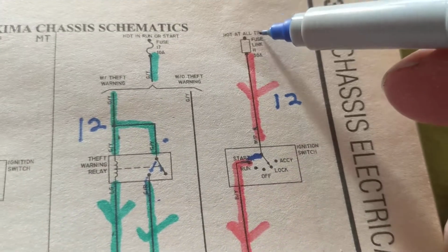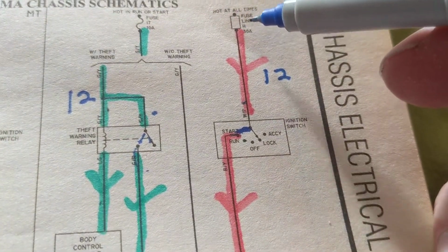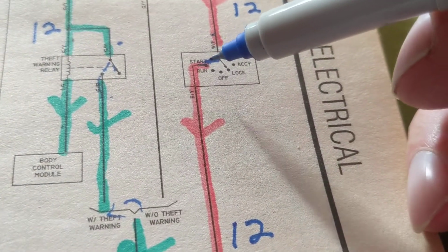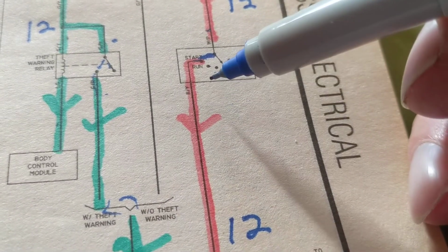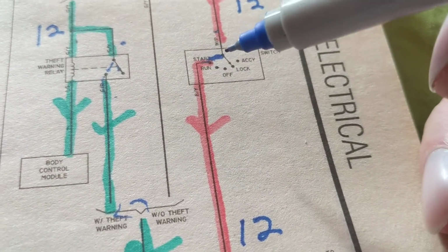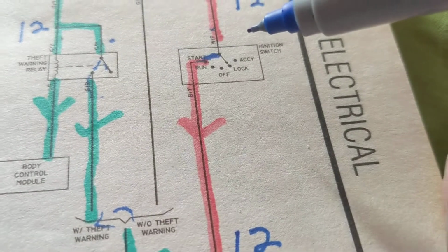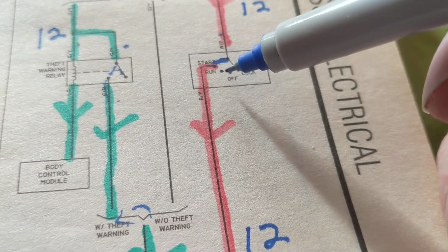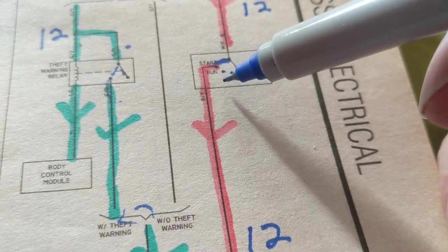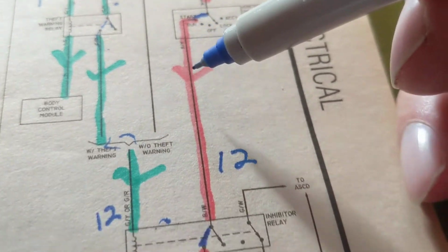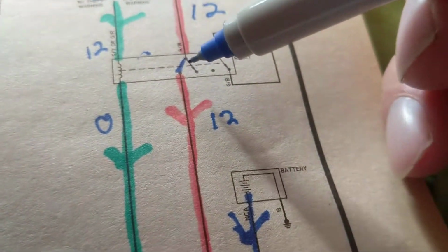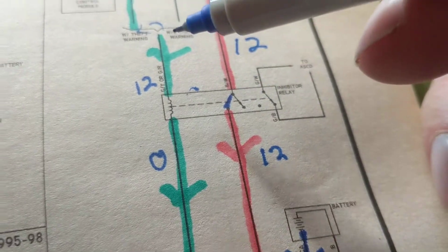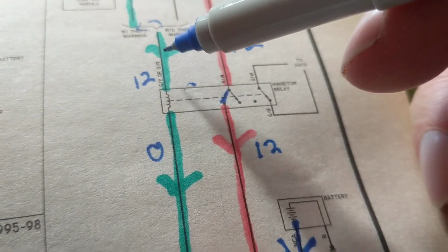The switch will allow current to flow from the battery through this fuse link, going this way, going through here, coming out the ignition switch in the start position. Only in the start position because we need the starter. Once it starts and cranks the engine, guess what? Put it back to run with no connection to the starter. So we start, we go here, we go here. Now what happens over here? If you remember a statement that I made, I said we allow current to flow.